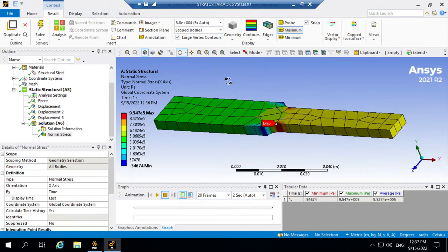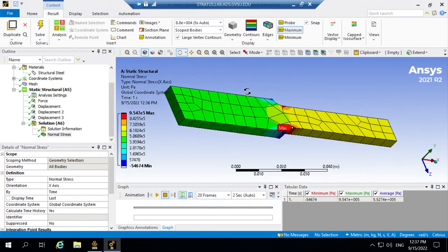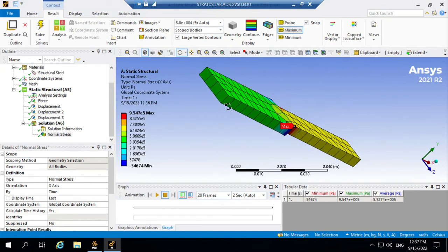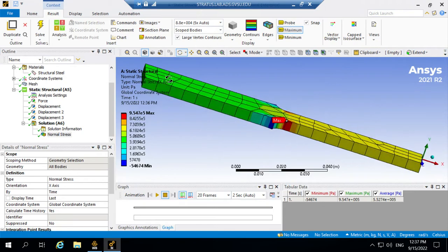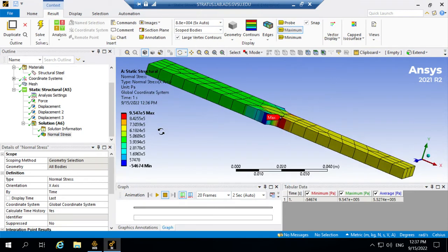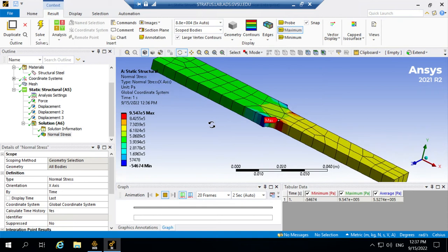This new type of boundary condition or support I put on this end kind of relaxed the stresses around here, right? And that's better modeling now because the max is happening here. See what I'm saying? Max is where I was interested. I was interested around this point, where the stress concentration was. So this is kind of better modeling, right?